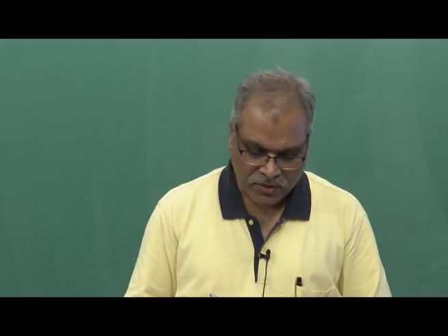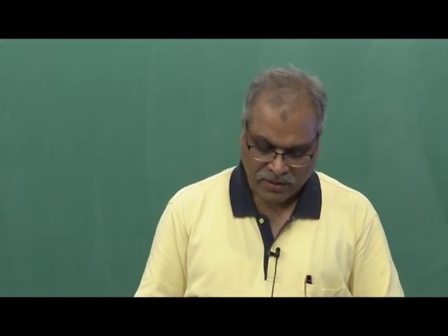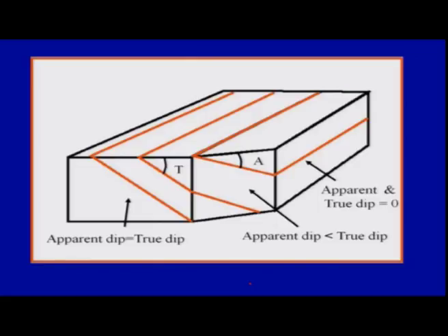So, in short, the importance here is that when you are doing the survey and trying to note down whether you are measuring the true depth or the apparent depth, you should look at more exposed faces of the exposure and take as many readings as you can, to determine whether you were looking at horizontal beds or actually at inclined beds. So it depends on what face you are looking at in the field, which is extremely important in talking about the attitudes of the beds.